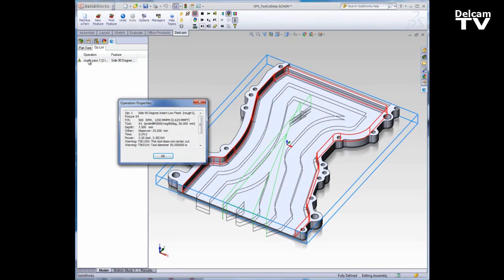An enhancement that's coming very soon in DFS is the ability to clear that equal cut setting so that you can have true 8 mm cuts, and then the last cut will get whatever's remaining. And there you see our step over of 25 mm. So this is exactly the behavior we expected based on those overrides.